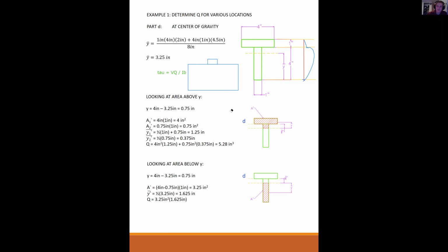Normally beams are wider at the top and bottom. Yes, actually, the beams are typically wider at the top and bottom because it produces the most efficient moment of inertia with the least amount of material. Yeah, this would be grossly inefficient, but it's not impossible.